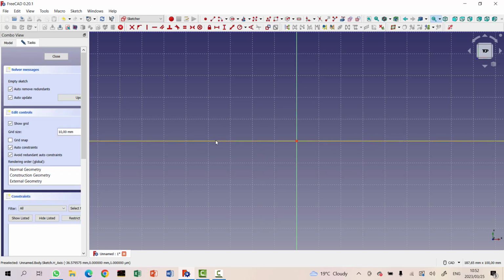Okay, so panel guides. What I want to do is create a panel that goes up that way, then that way, and up again that way. So let's do it like that with polylines. 1, 2, 3, 4. We'll start there, and I think we'll go up about 15. There we go. We'll set it to 15 soon enough. Up that way, and then we are going to go that way,